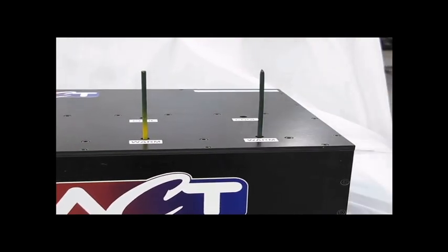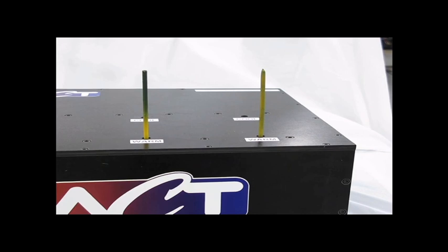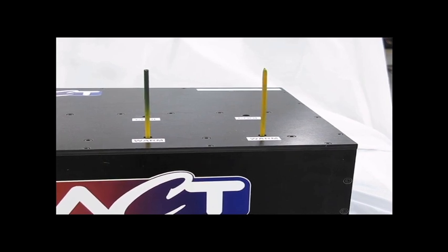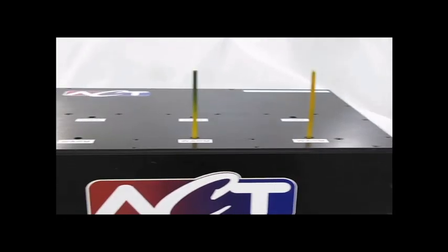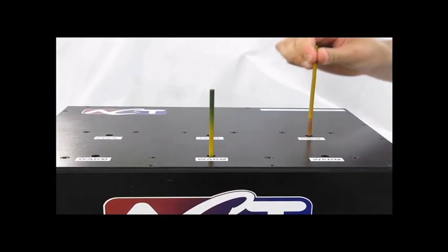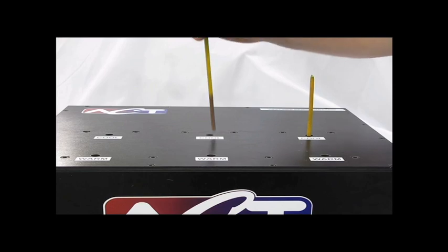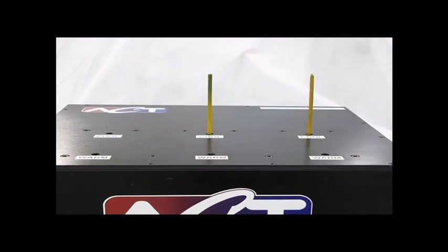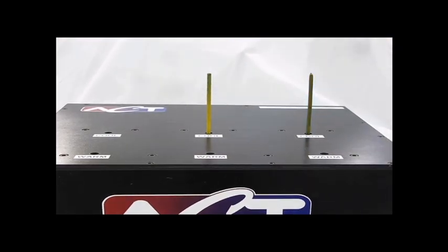Now we'll place the heat pipe into the hot side. Notice that the heat pipe reaches steady state almost instantaneously with minimum temperature gradient compared to the copper rod. Now we'll move both the copper rod and heat pipe into the cooler side. The heat pipe simply changes the direction of the thermodynamic loop and reaches the lower temperature steady state in seconds, while the copper rod struggles to reach that steady state temperature.